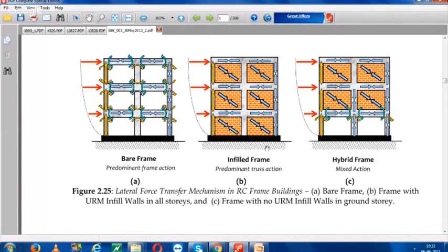In that technology I have increased the elastic property of a building by introducing viscoelastic link elements. Those link elements allow the building to deflect more and come back to its original position, and we are testing what effect it will create on the column, whether it imposes less shear force on the column. If so, our purpose is solved and our technology is successful.